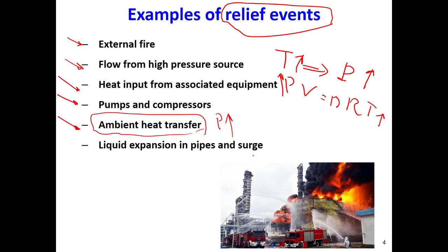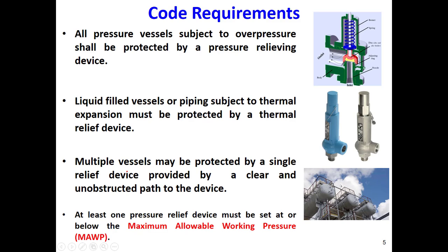Liquid expansion in the pipes or a surge tank are also cases in which we can have an increase in the pressure. Then code requirements. So these relief devices or relief valves in general have design requirements.